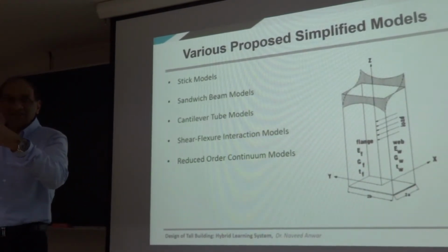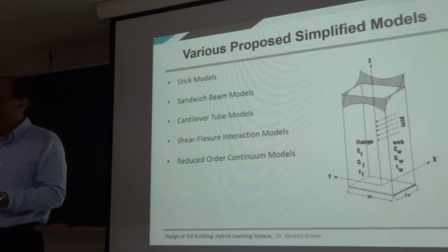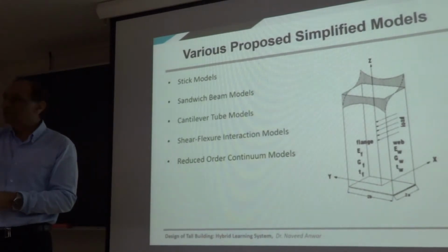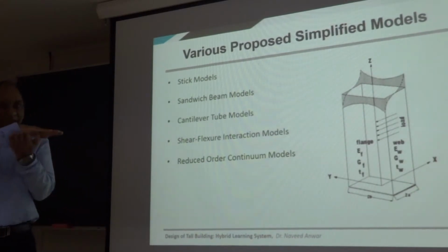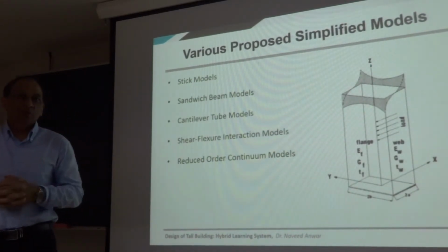Total weight of the building, total bending moment from the wind force, total bending moment from earthquake, and estimate what the mass per unit length will be, right? After that, you have those forces, then at each floor level, you can find what you need to resist those forces.